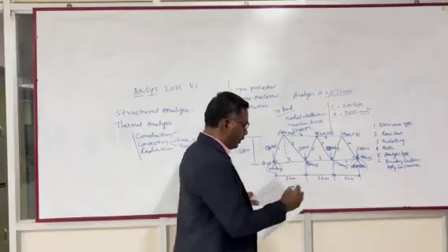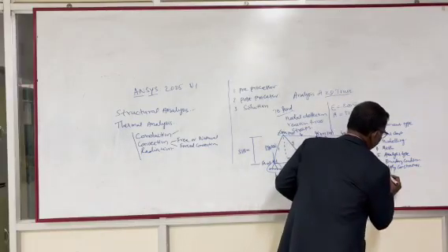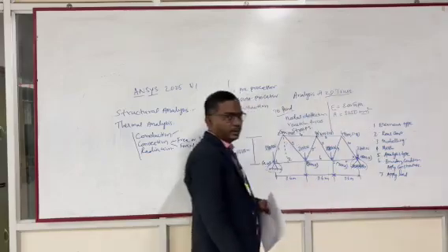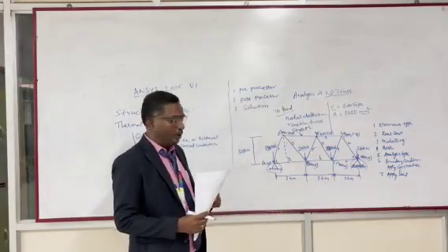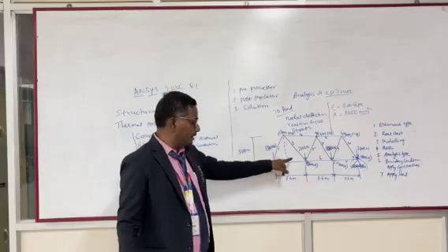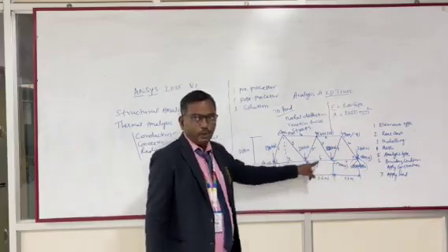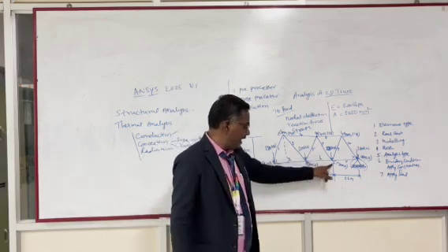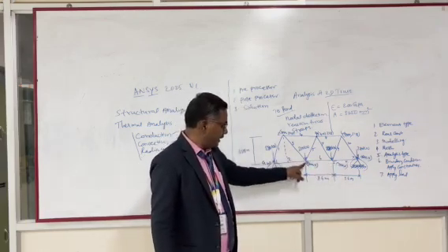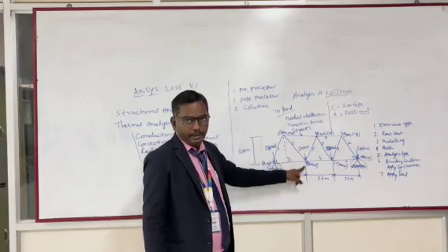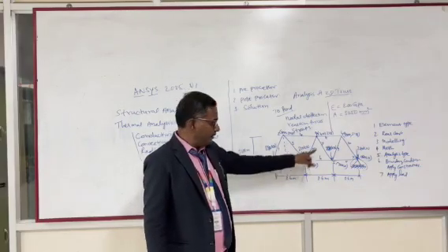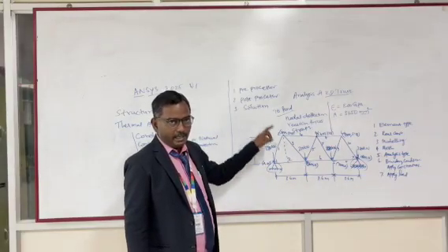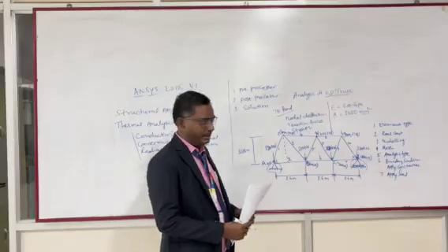And then we are going to apply the load. These are forces. Applying load. So this is the next step, applying load. So I told already, all the loads are acting in the downward direction. So the 280 kilonewton are acting at 1, 5 and 7, 280 kilonewton. The 210 kilonewton is acting at the third key point. You can select the particular key point and give a load is acting. So it is selecting the downward direction in the y-axis, downward direction. The value will be given in the applying load.